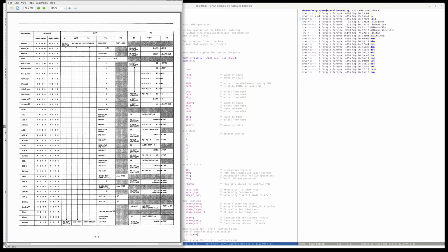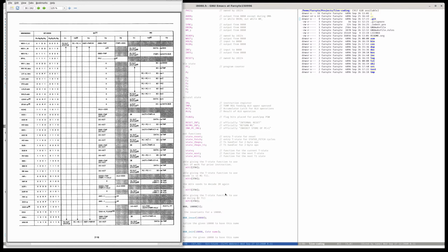And I believe it's 1-to-1, yep, because I have a separate T4 for each destination register. It'll know about its T5. So we do not need an M1 T5 in this case. So we may fill in M1 T5, but the M1 T4 that we use will not use that indirection. Let's go here. Increment, decrement, we'll do the same thing. It's a minus. DCR decrements by 1. I think I can use INX and DCX as well in the same logic to do register pairs.